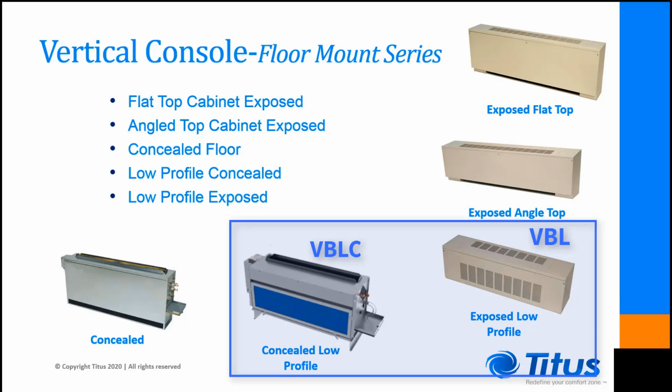The two units along the bottom right of the screen are the low-profile console units. They are much shorter than the full-height units, coming in at approximately 16 inches tall. These units are relatively very short as compared to the full-height units and fit well beneath tall windows. Unfortunately, in order to get this shortened height feature, unit capacity had to be sacrificed. These units are limited to approximately 600 CFM due to the height restriction.